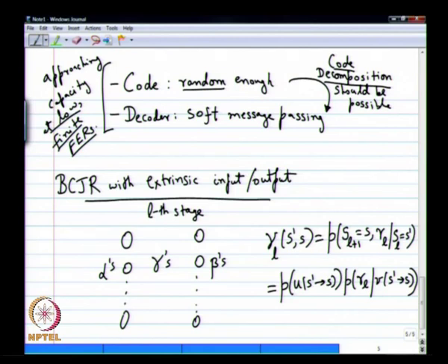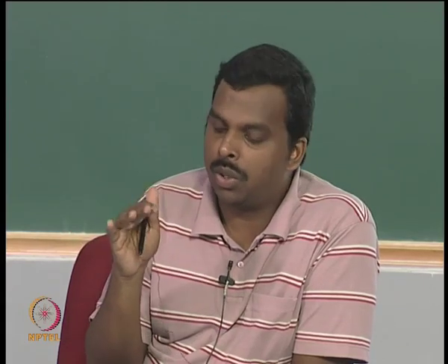Okay. So, this is the branch metric, and in this part there is no role for any extrinsic information. P of R_L given the particular two outputs is computed using what you received in the channel. It's just a normal PDF, you substitute into it, and you get 1 by root of 2 pi sigma square, e power minus (R_L1 minus V1) squared plus (R_L2 minus V2) squared. There is nothing you can do there with the extrinsic information or anything else.